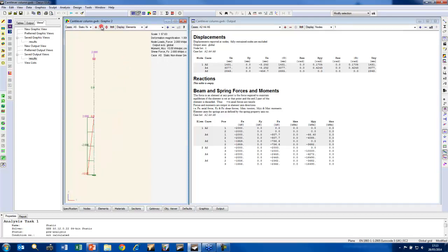In fact, with that level of horizontal movement and so little actual shortening, strictly speaking, that means that section increases in length. Not good. Whereas with the non-linear, we're getting a full rotation, and as we expect, we get a much larger vertical movement, which suggests to me this is a much more trustworthy result.